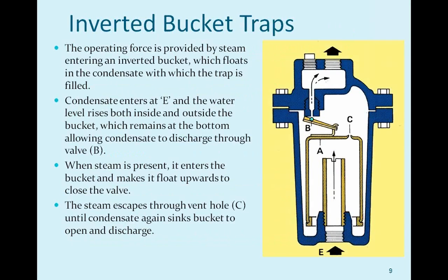Moving on to another very popular and prevalent type of technology, inverted buckets. This particular one is an inline, and then I also have a side entry one in another slide or two. These work on a very simple principle. Your steam or condensate comes in through, again, this is an inline, through here, and then condensate goes up and around the bucket and out the orifice.